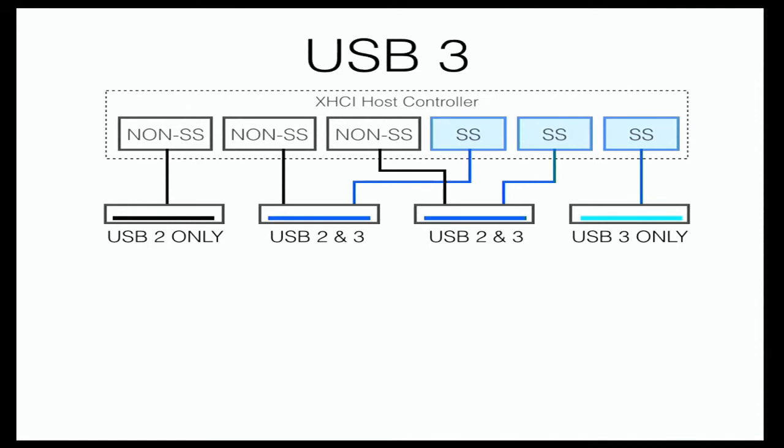How many people realize that when you have a USB 3 device with the little blue color in here, there are actually two completely separate sets of pins in this connector? Not many people do. And there are two completely separate sets of pins in these dual port connectors. One set of pins is connected to the super speed port on this controller, and the other set of pins is connected to the non-super speed port of the other controller.